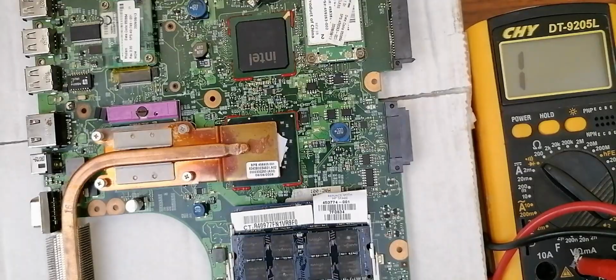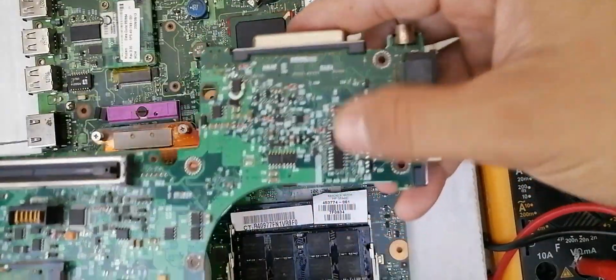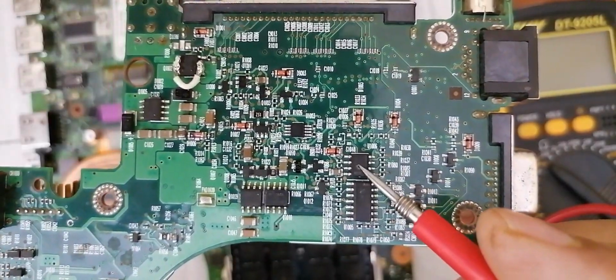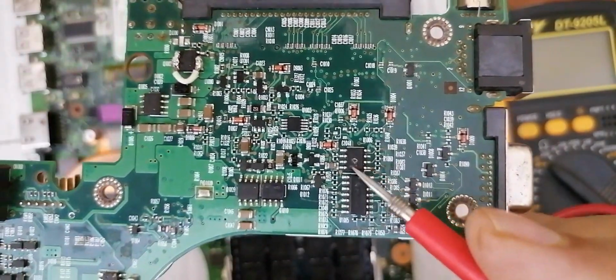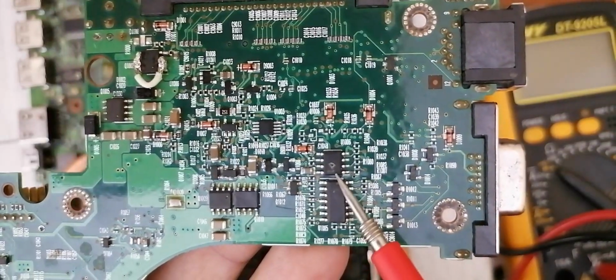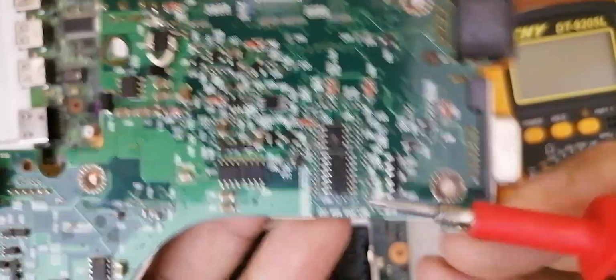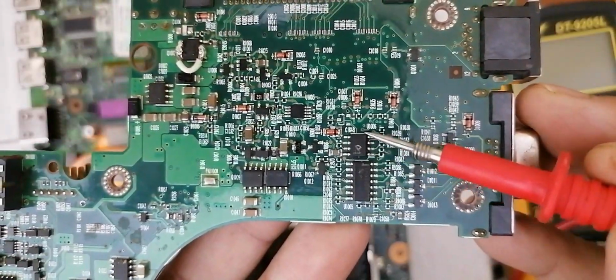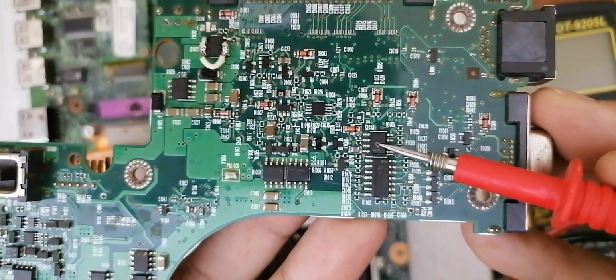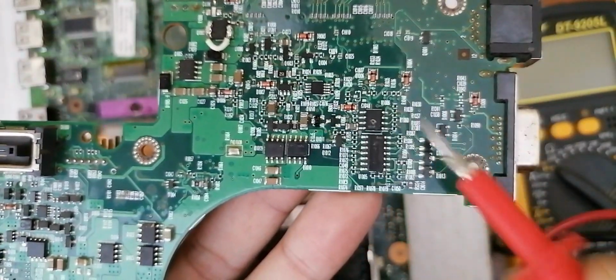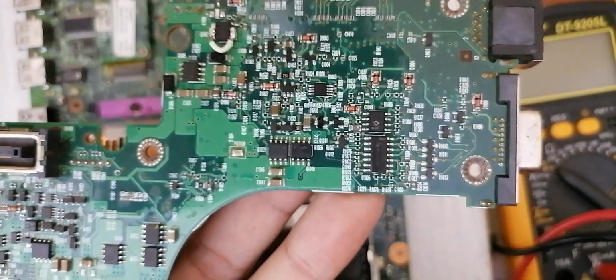I will show you a proof. For example, for this motherboard, if you do a visual inspection, you can find, as you can see, like this IC. Do you see this hole? This is a blown IC. So using just your eyes, the visual inspection, you can spot the problem. So now I can just replace this IC and fix the problem. Of course, it can be another component around it, but you should always do a visual inspection. Okay?